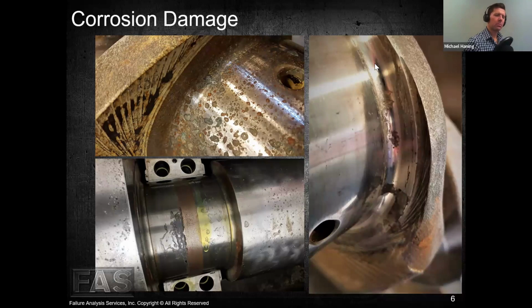And what's that yellow material there? Is that oil? This is oil, yeah, dripping here. And then you can see the rust right down the center line where it's a no contact area of the bearing.